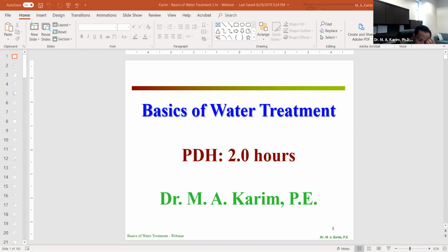So under introduction, the first thing that we usually need to know is the different types of water supply system. The first one that I have here by definition is a public water system, PWS. It provides water for human consumption through pipes, the pipe is the only option, for 15 service connections or 25 people, 60 days per year. So this is the definition of PWS.